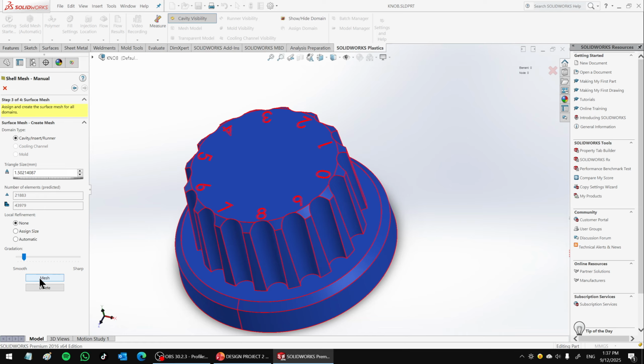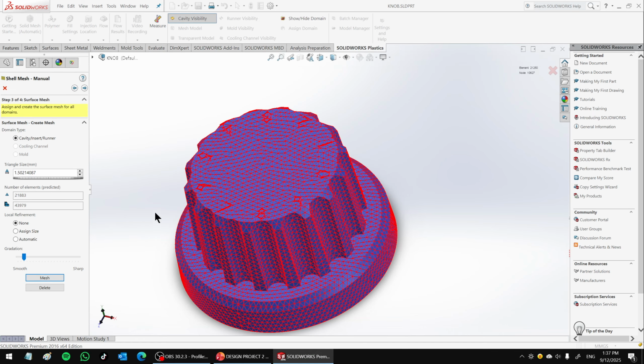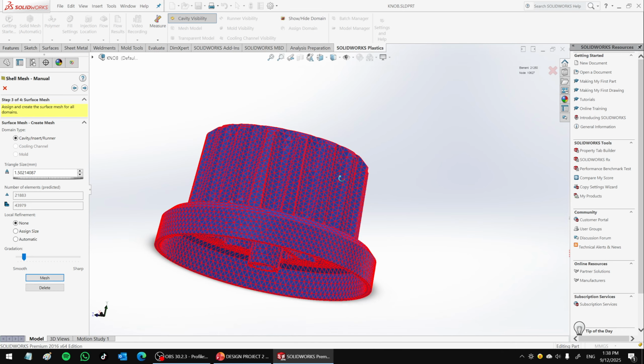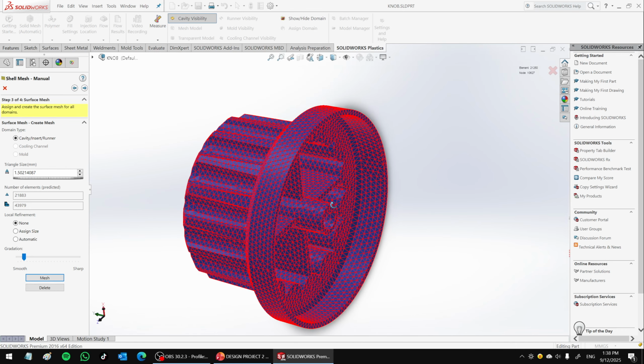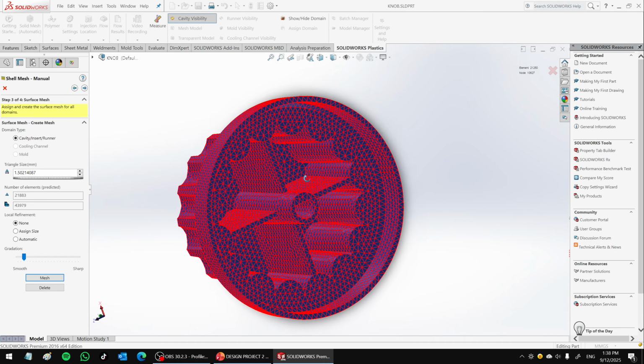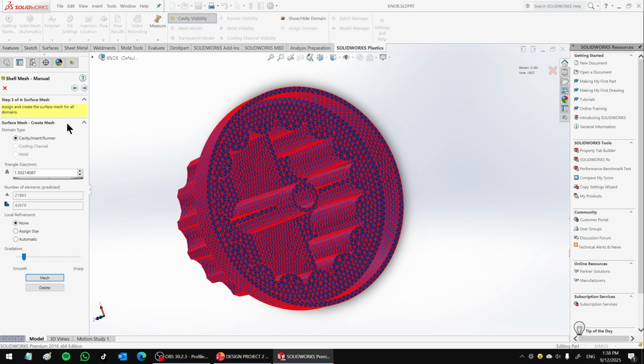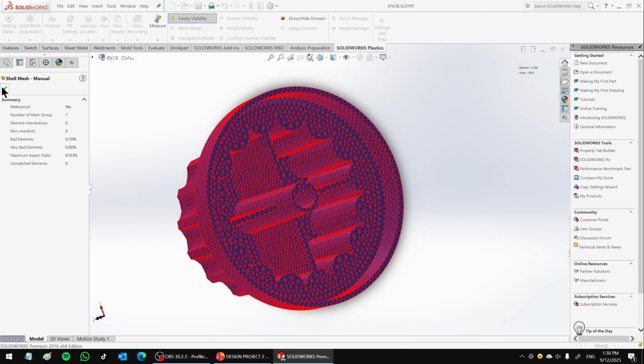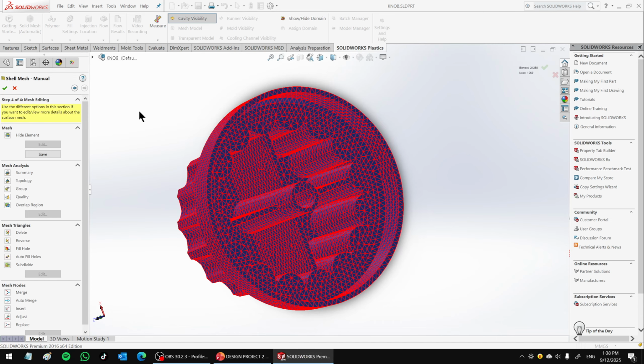So let's try to mesh. 21,000. That seems quite reasonable for 21,000. So I'm going to accept this one. So let's get a good number, 1.5 mesh, just so that we can repeat. Mesh is done, click next. And then click OK. And then click OK one more time.